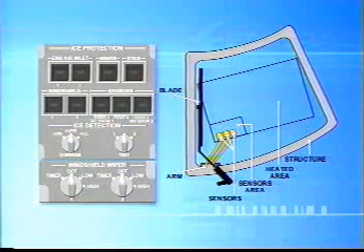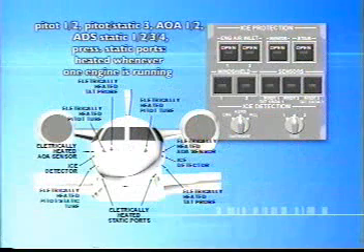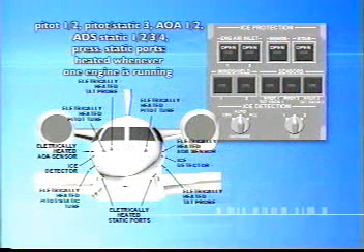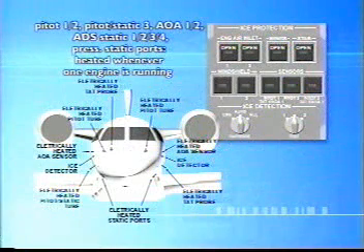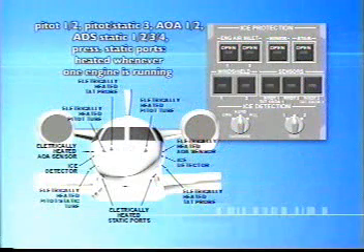Sensors are heated according to a dedicated logic. Pitot 1 and 2 and Pitot Static 3, AOA 1 and 2, ADS static ports 1, 2, 3, and 4, and pressurization static ports are heated whenever at least one engine is running.